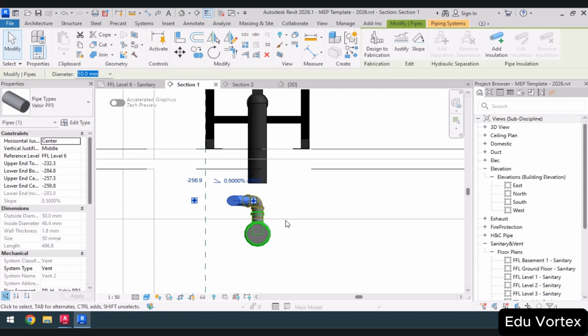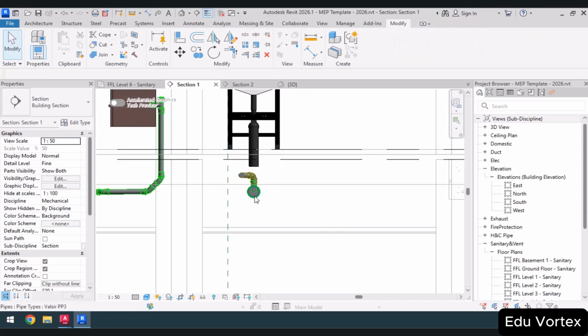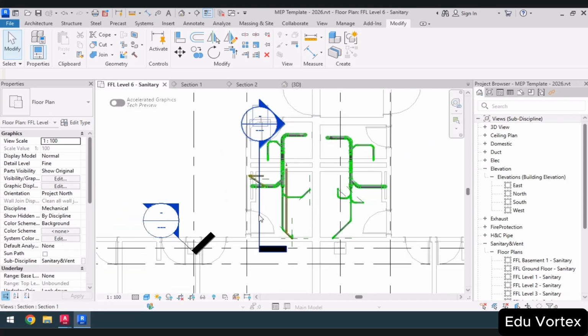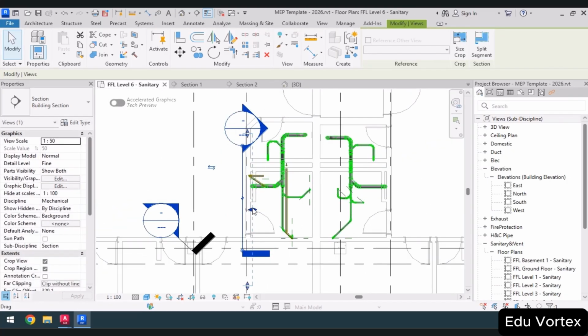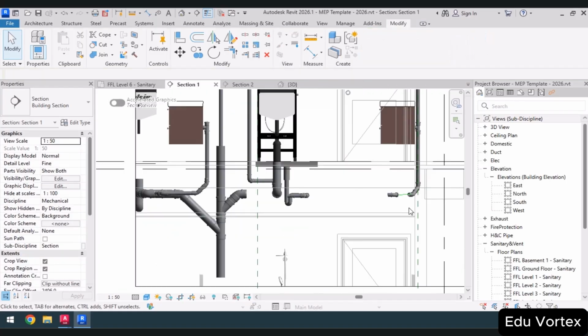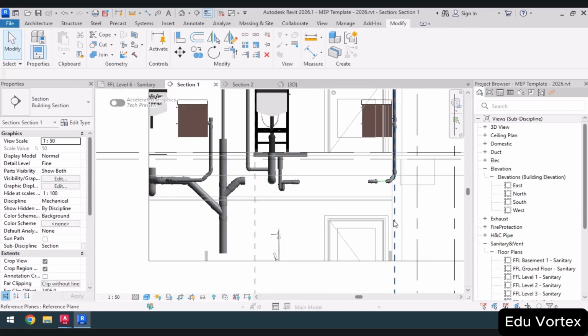It appears that when we brought it down, it came out of the ceiling, so all pipes need to be lowered in height. To adjust the height, I will create a section that clearly shows this line. So right click and go to view. Since the 45-degree connections have brought it lower, it will be very easy to adjust.